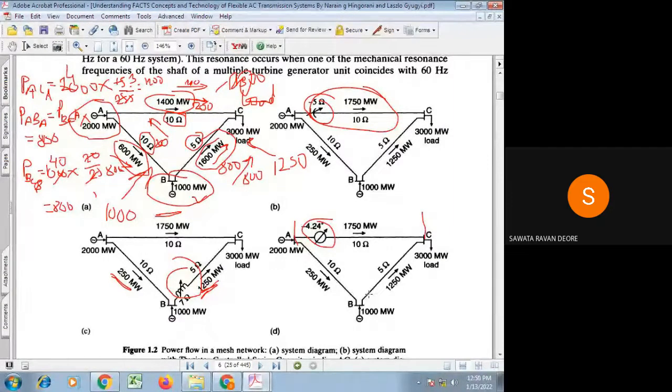Now we need to think economically and technically whether to go with the upgradation of the line or to go with the FACTS controller devices on the line, which one becomes more economical and so on. So according to that it can be done. Obviously, by providing the FACTS solutions here we diverted it, but as in future the demand goes on increasing, one of these two lines may get overloaded again. Suppose the rated load is reached.